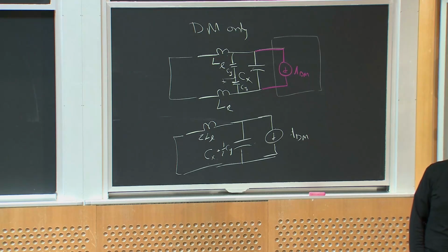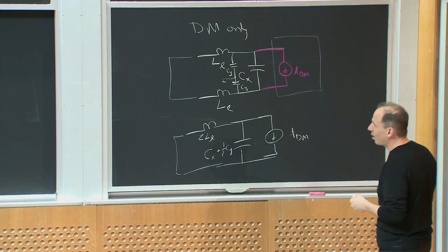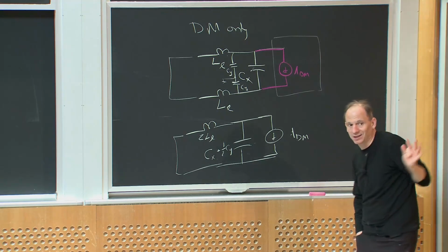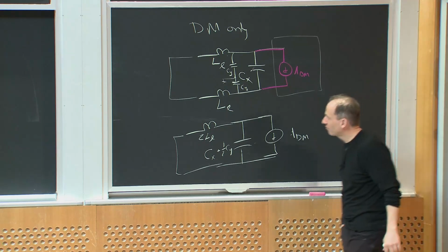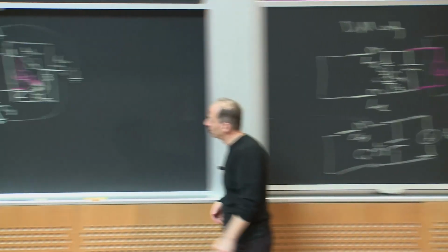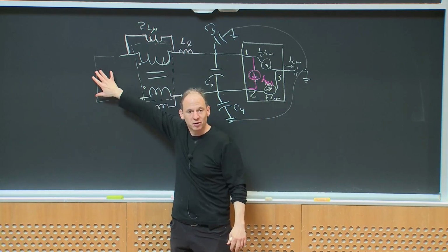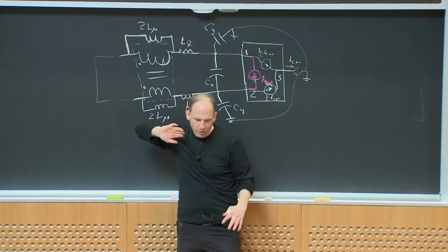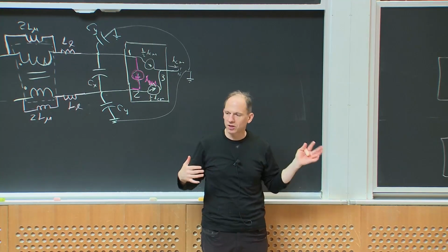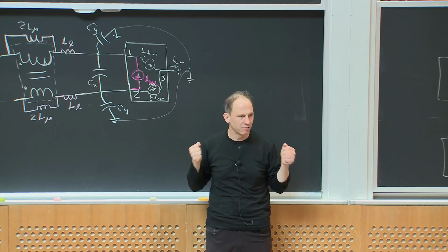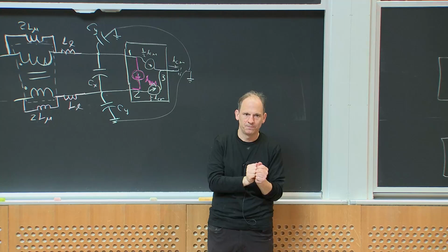If the thing that's killing me is differential mode noise, then I might as well not worry about the magnetizing inductance because it's not helping me. I ought to focus on the X capacitor and the leakage components, or adding in another filter stage and worrying about the leakage components. So we can really think about the strategy used to design these filters in terms of the common mode and differential mode components, and I'm using different elements to help me build the filter and pass the specifications.